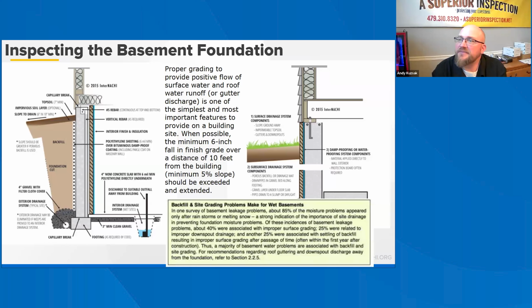Moisture problems are often found in the basement of a home or building. Even in dry site conditions, foundations are continually exposed to moisture vapor from the ground. When basements are used on sites with high groundwater or in areas with fluctuating ground moisture levels due to rainfall and water table changes, they are frequently exposed to bulk water. Therefore, foundations must address potential water leaks through cracks and joints, capillary movement of water through foundation materials, vapor transmission of moisture through foundation materials, and condensation of moist air on cool foundation surfaces.